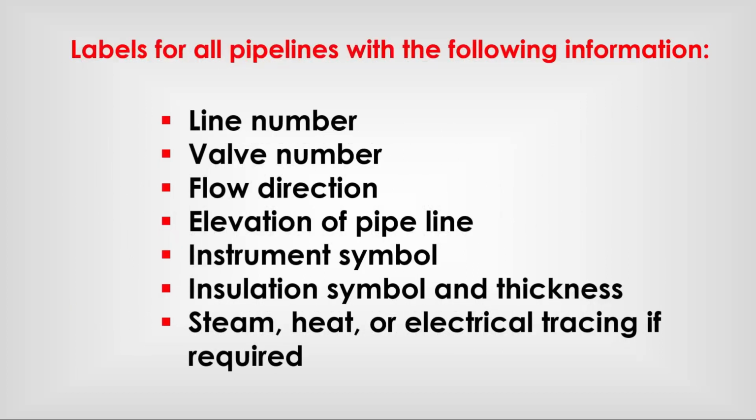Labels for all pipelines with the following information: line number, valve number, flow direction, elevation of pipeline, instrument symbol, insulation symbol and thickness, steam, heat or electrical tracing if required.